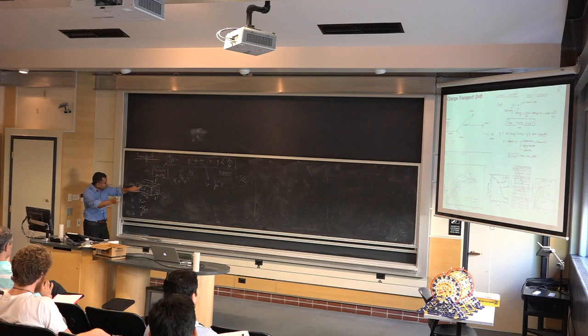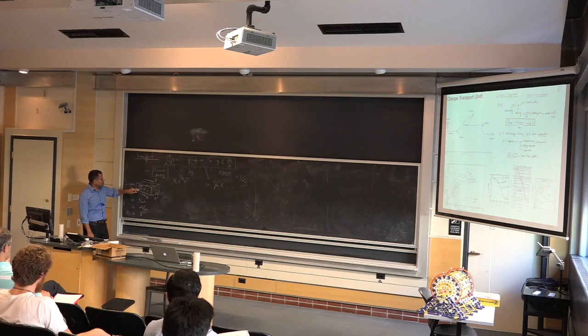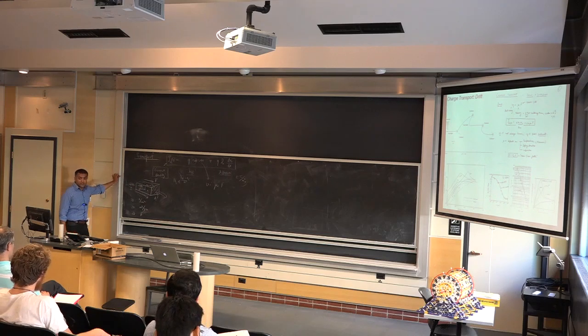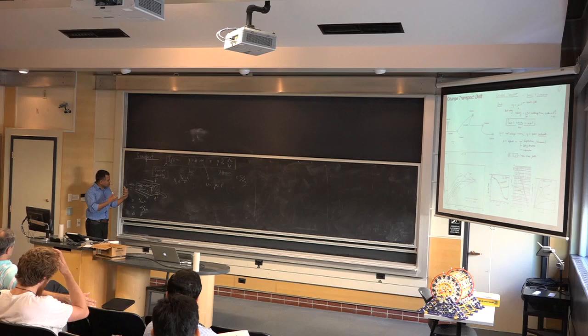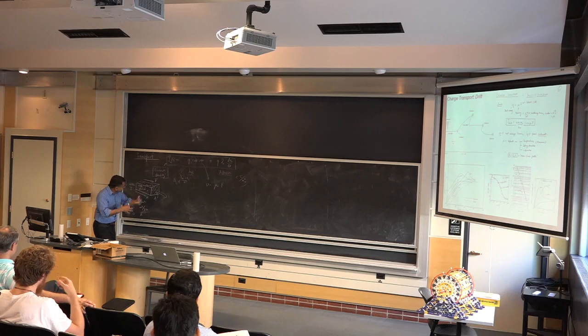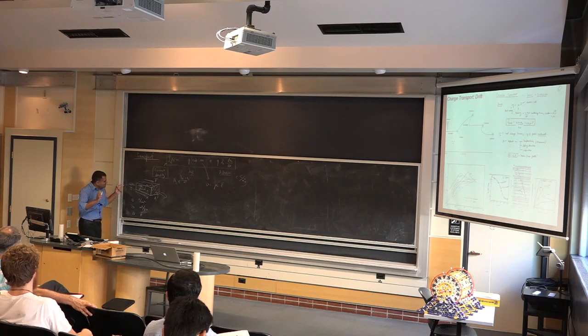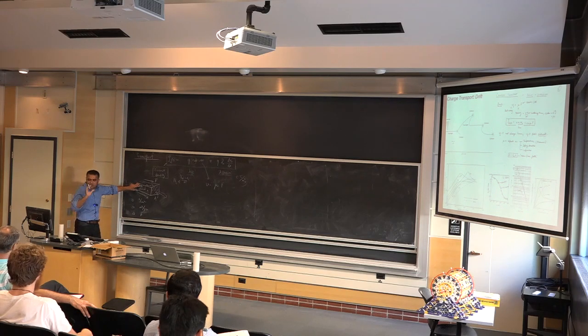So the current will also saturate, and that was somewhat of a mystery in the 1950s, because people had always measured current as a function of voltage, and in metals it is always linear. Then suddenly they're measuring germanium and it starts saturating. Why is it saturating? Shockley came up with the idea that the carriers collide with the lattice, setting off vibrations, a heating of the lattice. It's effectively Joule heating, but because of phonon scattering. Essentially, it loses its energy into the phonons as it collides with the lattice.